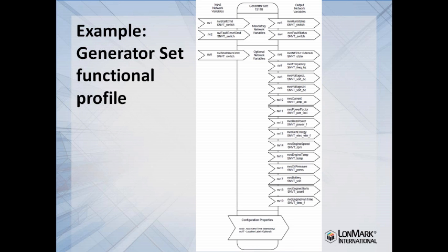That is how LonWorks devices normally communicate. And the basic level of standardization here is that LonMark has defined certain standardized network variable types. This makes it very convenient to make different devices from different manufacturers talk to each other, so you can integrate them in a uniform system.